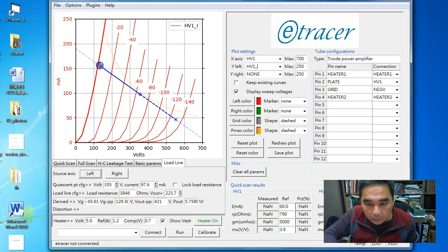It's for the positive half of a full sinusoidal wave, and this X here and this dashed line are automatically updated because we know this curve will never be symmetric. The gap between the curves gets narrower and narrower as the bias gets more negative, and that's the reason where the even order harmonics come from.